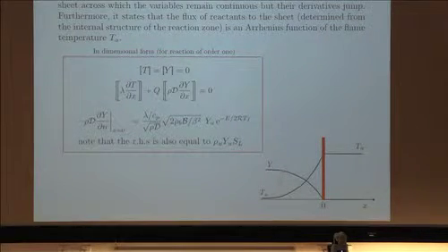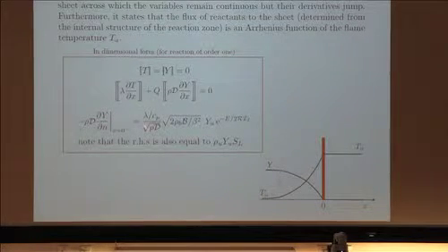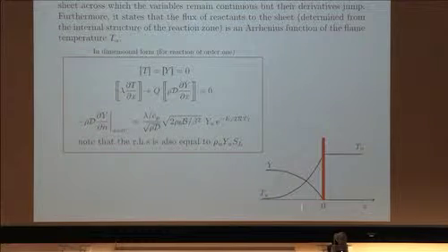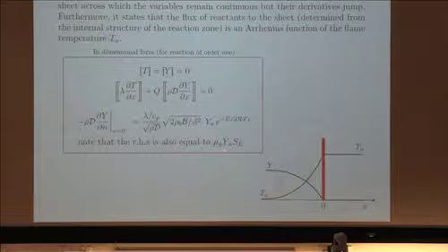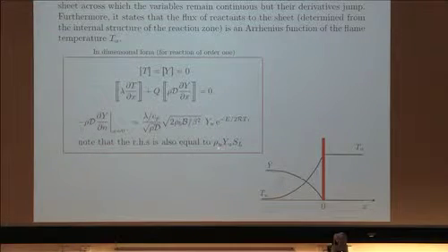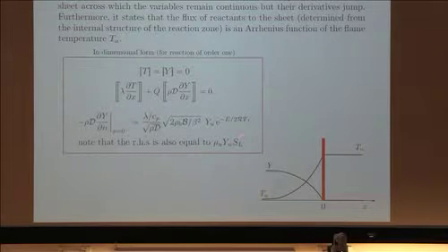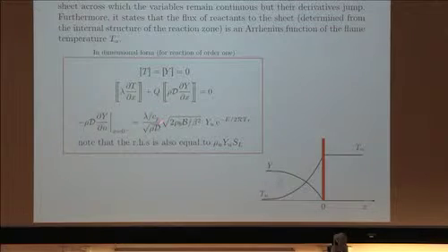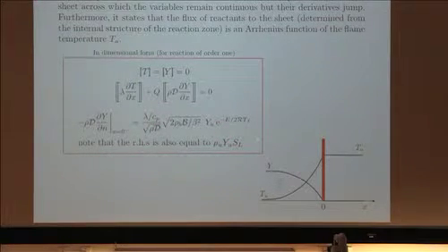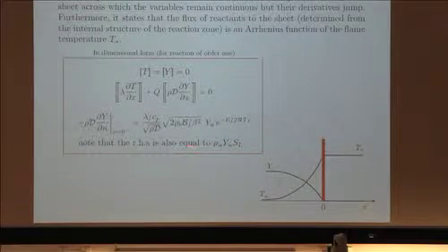In other words, for the planar steady propagation, this needs to be the flux across the flame. Note that the right-hand side can also be written as essentially a flux, rho u, Yu, which is the mass of the fuel multiplied by the velocity, the laminar flame speed, okay? Because part of these terms are equivalent to the expression of the laminar flame speed that we derived. In other words, this is just direct substitution.